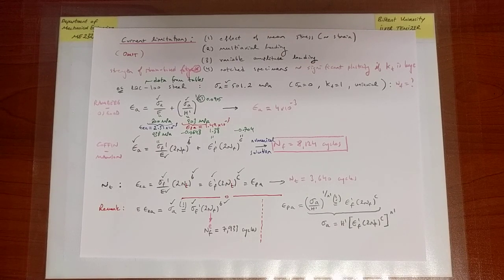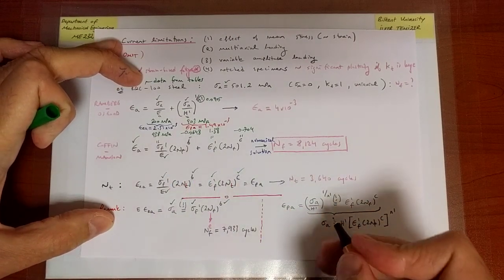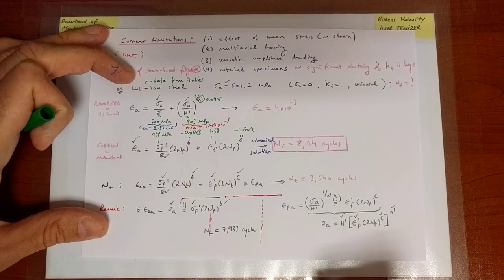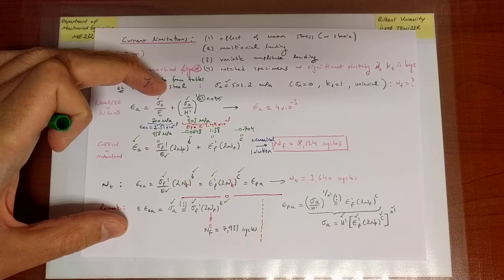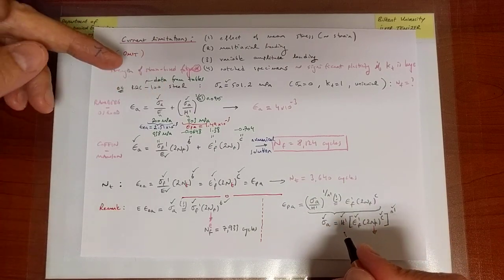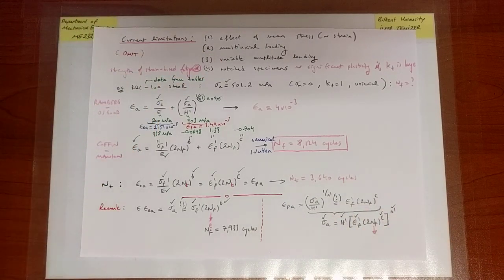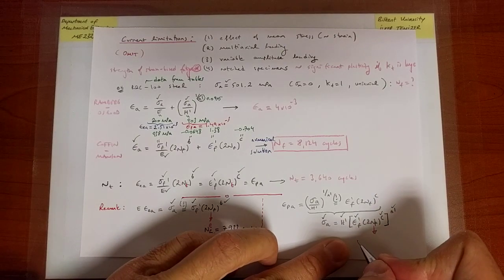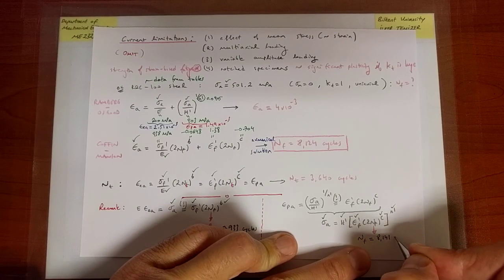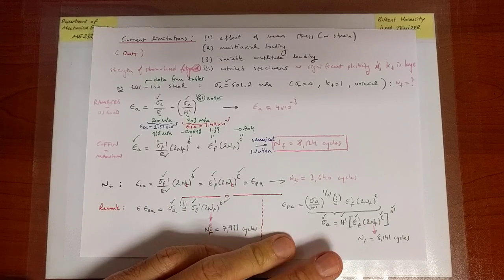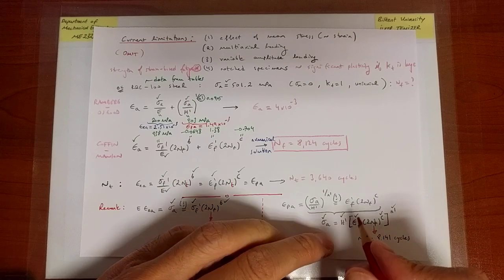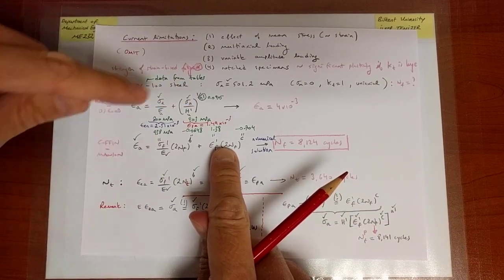Okay, so here I also know the value of h prime. I know the values of epsilon prime f, c, and n prime are given. And I can go ahead, therefore, and solve for the number of cycles to failure, because sigma A is also given from the outset. So I don't have to go through this trouble. Given sigma A and all the material constants, I can use this equation if you like. And the result is NF equals 8,141 cycles. Okay. Now let me call this NFP, because it's a stress-based life prediction based on the plastic contributions to these two relations.